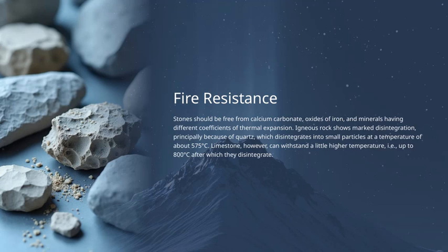Let's talk about fire resistance in stones. It's important that stones are free from substances like calcium carbonate and oxides of iron, as well as minerals that have different coefficients of thermal expansion. When these are present, the stones can become more vulnerable under high temperatures.